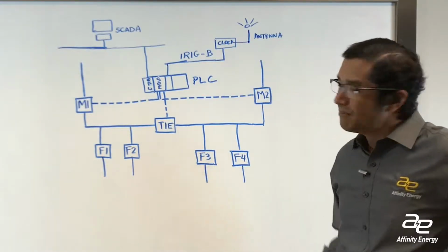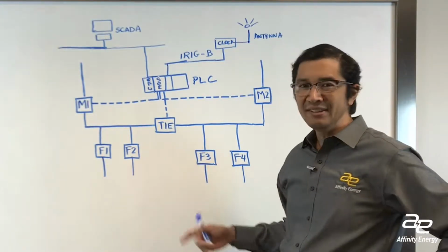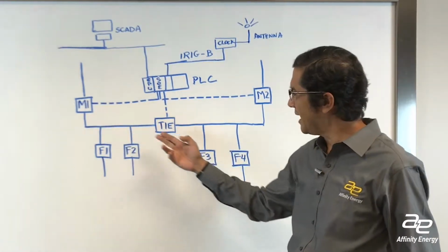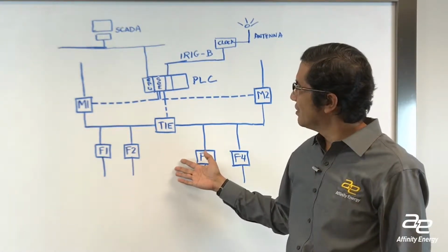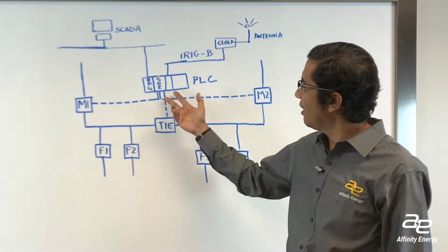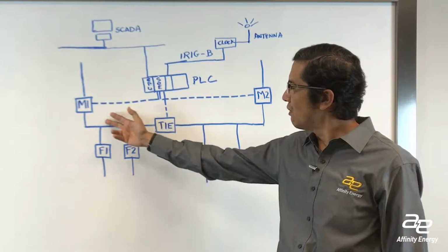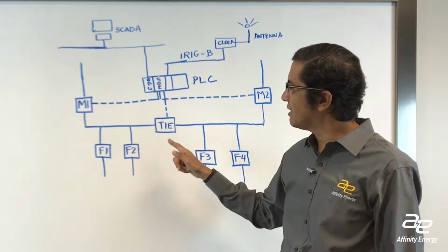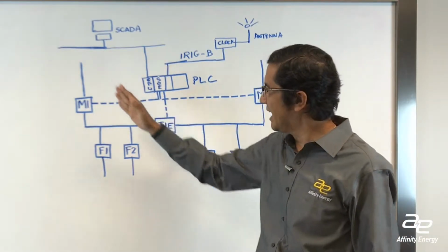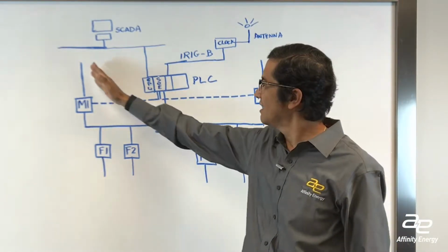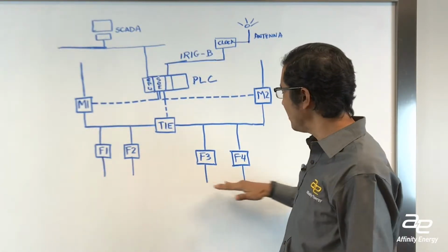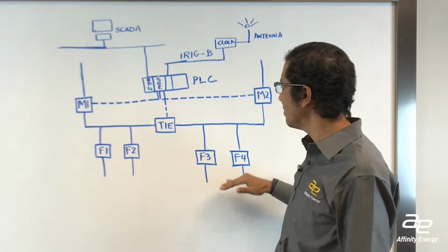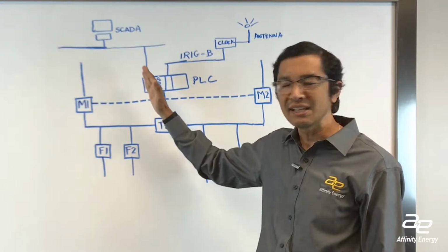What I've got diagrammed here is a double-ended substation. So again, it's a main-tie-main, and for my particular scenario, what I'm going to do is look at the importance of a PLC that's controlling these main and tie breakers, assuming that it's looking upstream to make sure that it's got two sources of power and making sure that these feeder breakers are obviously being fed power by one of the sources at all given times.